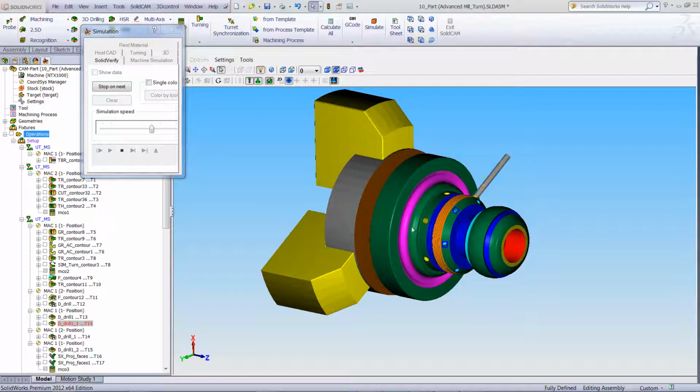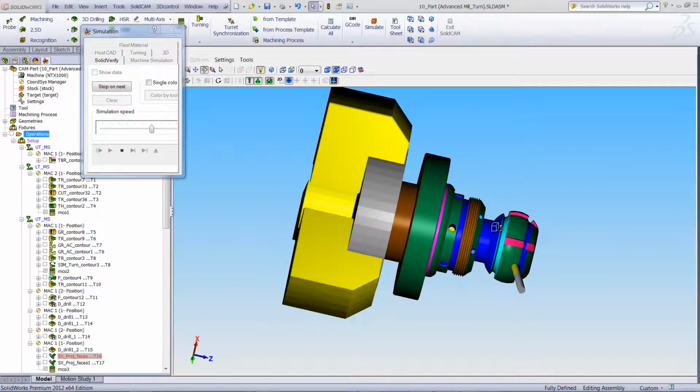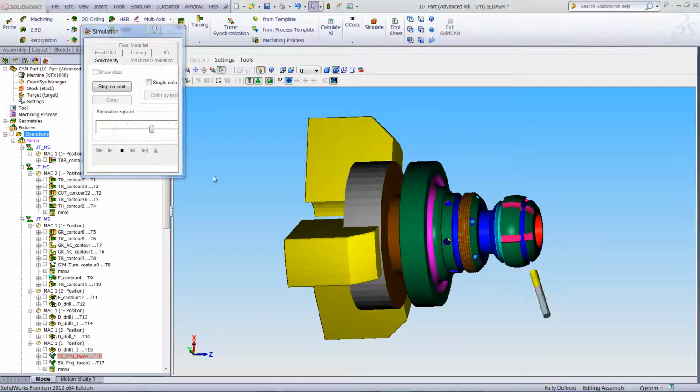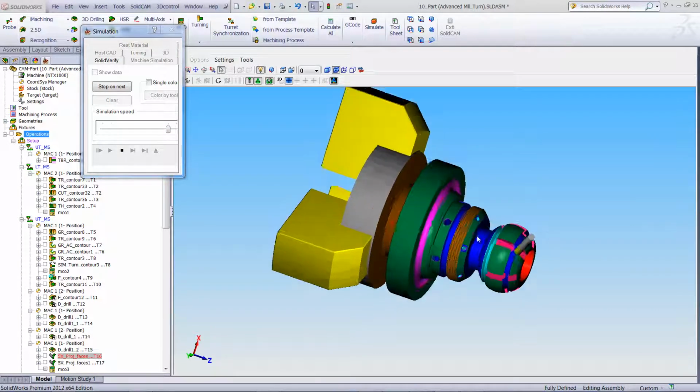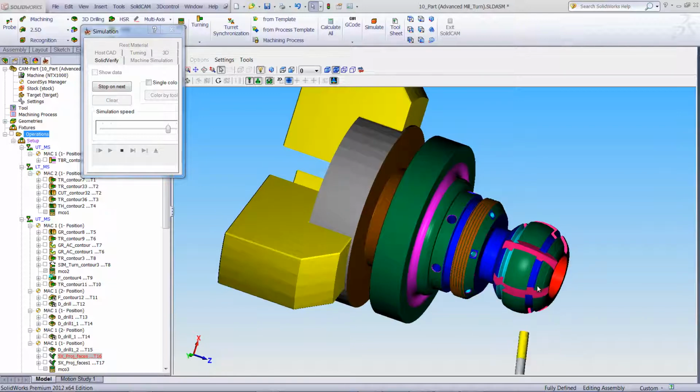And this is going on this circumference over here as well. When it finishes the drilling, as shown over here, it'll then do these slots using the fourth and fifth axis of the machine to do this simultaneous on these slots over here. And you can see it's doing each slot, stepping down, going from one to the next, completing it, and then continuing on to the next slot.